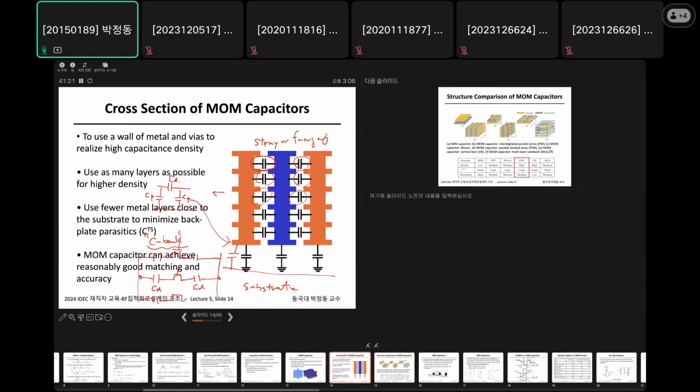If we implement like this, this is called a capacitor bank. Unfortunately, if this is on, so switch on, then it forms something like a CD over half, right? So let's say this is 2 CD over half, this is 4 CD, then it is something like a binary code, binary capacitor bank.